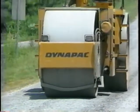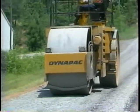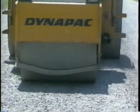Steel-wheeled rollers have been used successfully for compacting chip seals and can be used if a pneumatic roller is not available. Steel-wheeled rollers are not generally recommended because they can crush aggregate and bridge over low spots in the pavement.